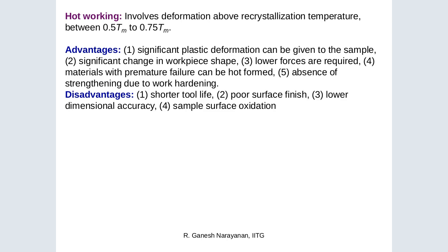Number two, a significant change in the workpiece is possible. Number three, lower forces are required because when working in a very hot environment, the deformation is very fast. Number four, materials prone to premature failure can be formed. And then, absence of strengthening due to work hardening.